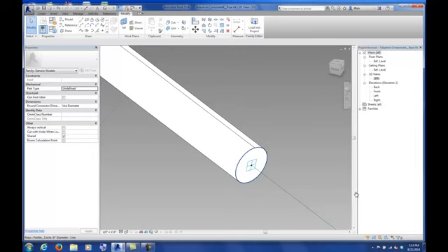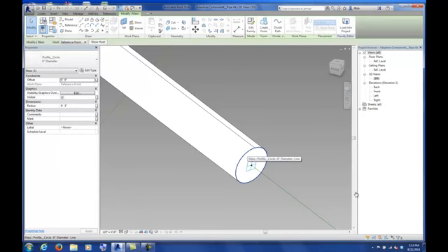What I want to do is tab over until I find where it says Mass Profile Circle 6-inch diameter line, and left click on it. Everyone get that to work? You should know that you've selected it because off to the top left it says Profile Circle 6-inch diameter, and then it has a radius here and a particular dimension here.